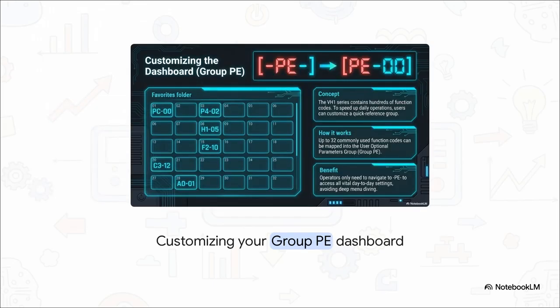And here is the absolute ultimate operator's shortcut. The VH1 has hundreds of function codes. Diving through 3 levels every single day for your 5 most used settings, that's a huge waste of time. The solution is Group P. Think of this as your fully customizable favorites folder or dashboard. You can map up to 32 of your daily essential parameters directly into this one group. By doing this, you completely bypass the deep menu diving, bringing everything you need for day-to-day operations into one highly accessible spot.